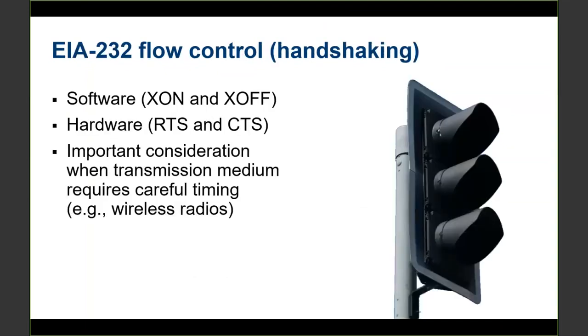Okay. That being said, if you are using hardware handshaking, that's great. There are settings where you can add in delays and things of that nature. But if you're not using hardware handshaking, basically if you're not using the right cable, and we're going to talk about that in an upcoming slide, then you really don't want to tweak those timings if you're not even using hardware handshaking, if that makes sense. It's important to know if you're using hardware handshaking, software handshaking, or both.